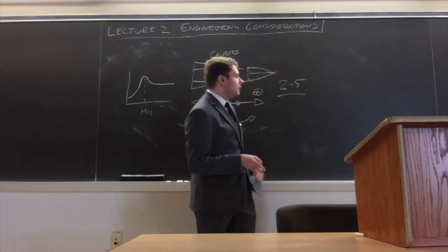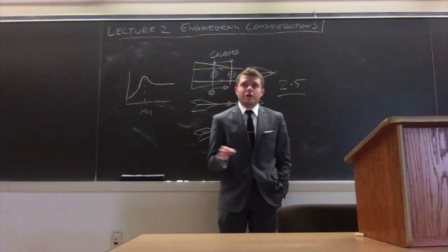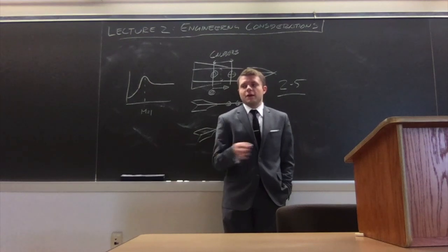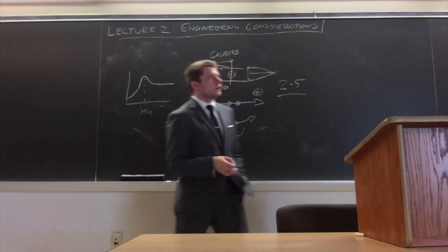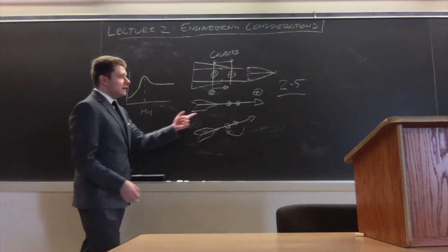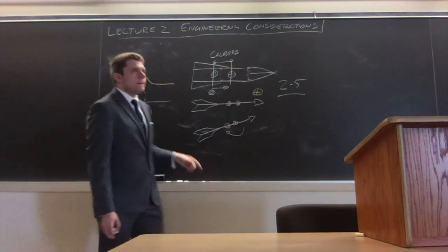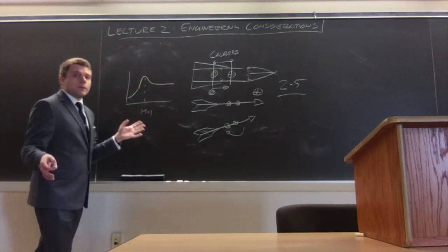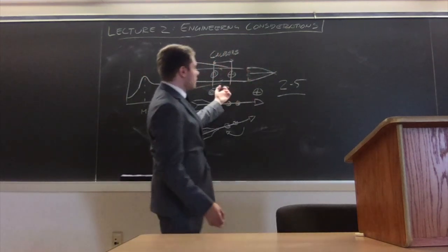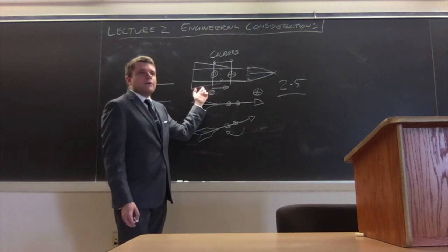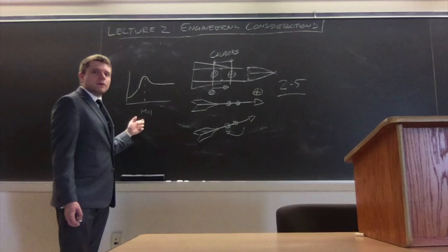It will actually simulate the behavior of a rocket at high Mach, and it will tell you how your center of mass and your center of pressure will shift as you go past the sound barrier. That means you can actually design for that when you're building your rocket. You can have it so that you maintain the same level of stability even after you go supersonic. For our purposes, an orbit-capable rocket is one that uses a completely passive system, using fins for stability. We have to consider that this thing will be stable on the way up.